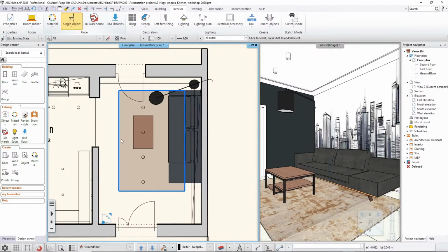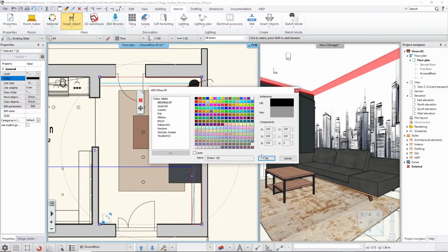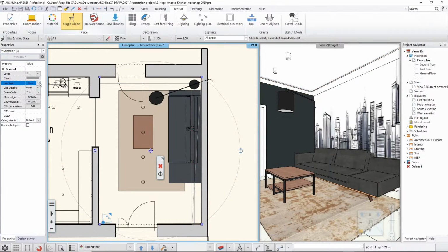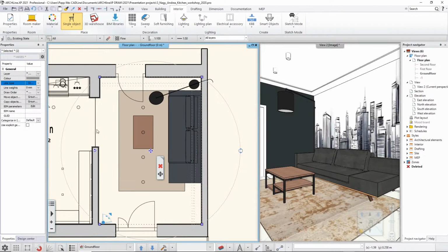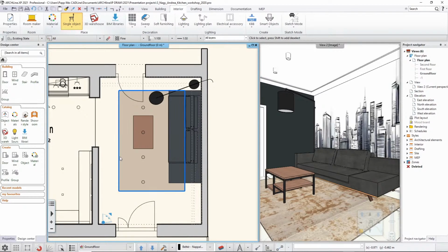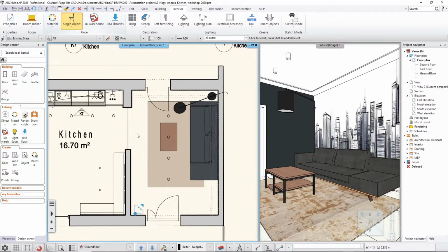It is a very simple and very powerful tool to organize your drawing and make it easier to read for your clients and for yourself. Also, by extending this with other things, like, for example, let me just change the color of these supporting parts and use, for example, a dash line here, and then hit OK. And now my drawing, with a few clicks and using the 2D fills and the drawing orders, is much easier to read and much easier to understand, and this is what I will publish in the final drawing. So this is how easily you can reorganize the content like I did.